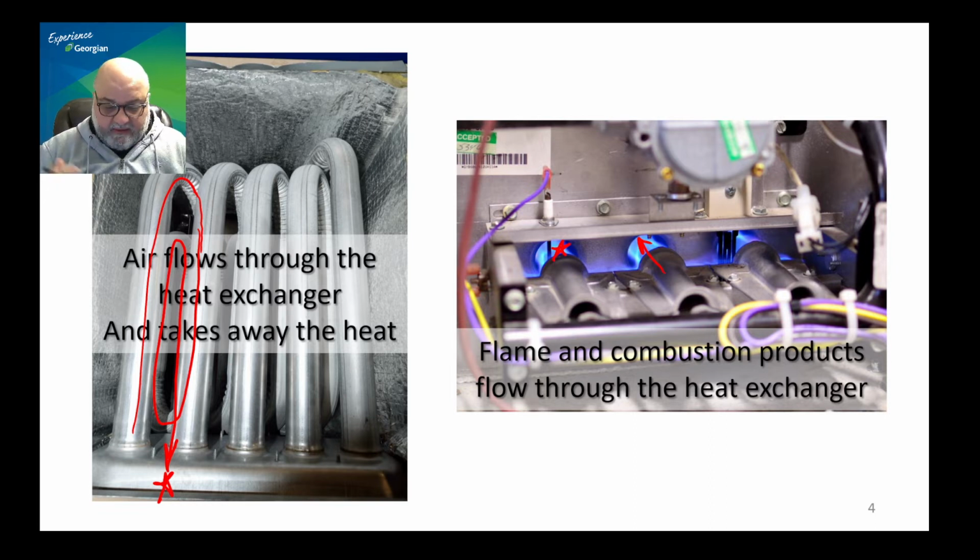The idea is to control the draft, meaning the idea is to move the combustion air and gas which come through here, right? That black opening here is for combustion air, and this is going to be the orifice that shoots in the gas under pressure, albeit it's very, very low pressure, 3.5 inches water column.